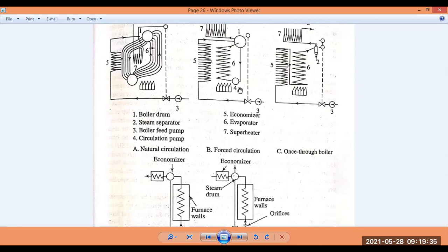water and vapor portion in the system itself. So liquid water is directly and totally converted to steam at the critical pressure. So the question of moisture, filled with water particles, will not arise here. Now here no drum is necessary because you are not accumulating or storing the water-vapor mixture. Here total water is converting into steam, so nothing is required to be accumulated or circulated.